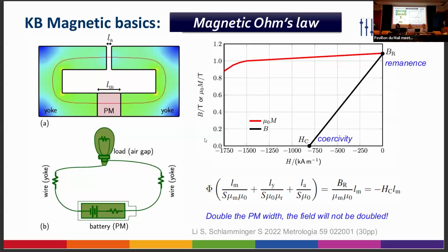If we want to calculate the magnetic flux, you have to know the MMF, right? For the PM, I'm not going into too much detail on the basic theory; you can find it in textbooks, but we can write this. Just remember, the PM MMF equals minus Hc times LM. Hc is the coercivity of the permanent magnet.